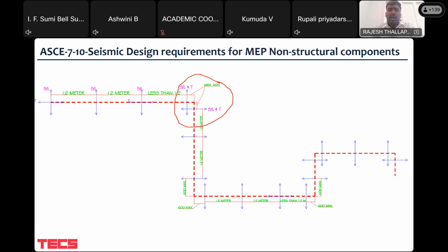And so the hydrostatic pressure is going to be very huge, and also it's close to like 12 bar pressure. That's a maximum that comes in a building. You can relate to any building. So that's a maximum 12 bar pressure which has to be designed. So a 12 bar pressure is huge, that it can burst off a complete one-story building. So it's that pressure. So when this pressure of water is coming and a seismic incident, and this impact of seismic is added on top of it, all the piping will just get burst up when we are not restraining it from all four sides in order not to move.